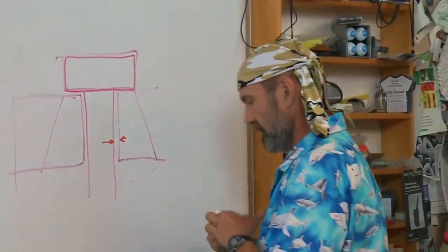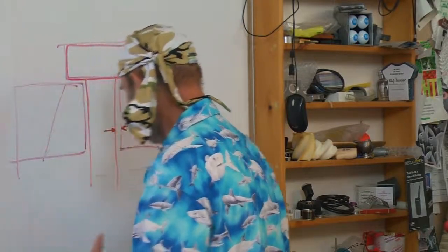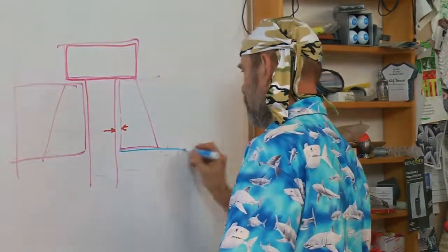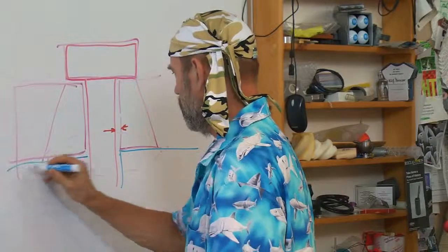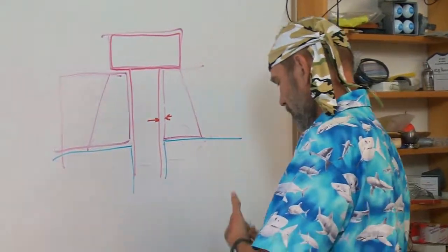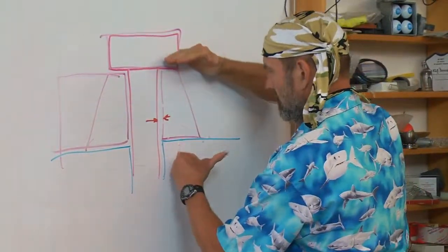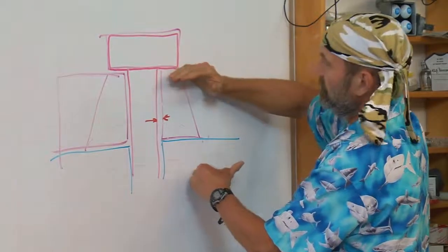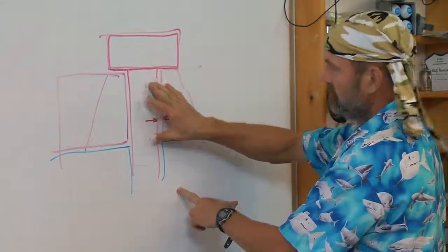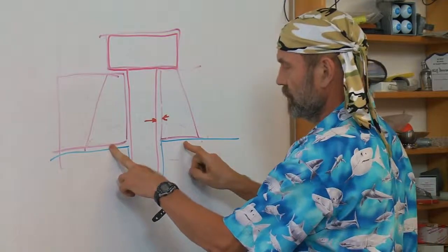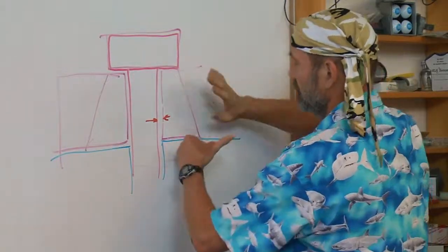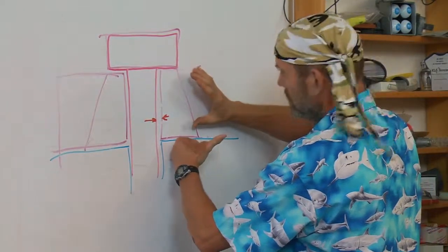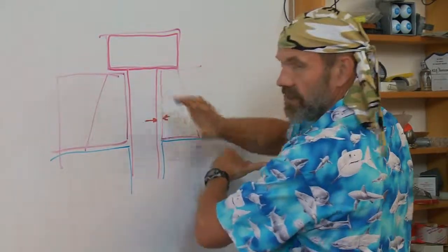And if I want to keep one part from slipping against another, it's by compressing the two, then the force in the bolt times the coefficient of friction is what gives the bolted joint a resistance to sliding.